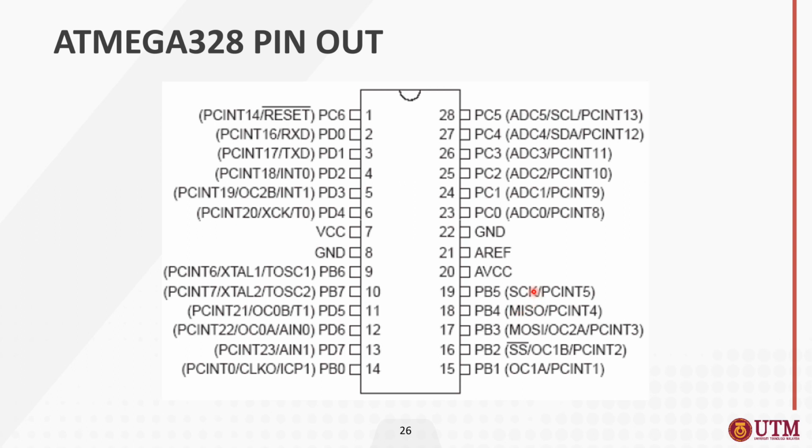And then SCK is the I2C pins, right? And then you have AVCC, which is the analog voltage supply, and then AREF is the analog reference voltage. If you want your sensors to have a different type of reference voltage, you can connect it to this pin.